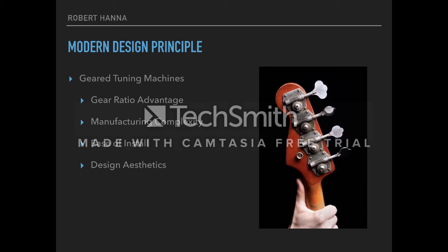So I've seen tuners all the way from 12 to 1 to 18 to 1, meaning that for every turn you have 12 to 18th of a turn of the capstan per degree. So what this does is it allows us to have more robust design, and some of these things I'll go into a little bit more in depth later, but it also allows us to more finely adjust the pitch, so we're not passing the note. With the violin, it's very direct response, so that can cause some problems, but high gear ratios can also make things really slow to turn, so usually don't go above 20.